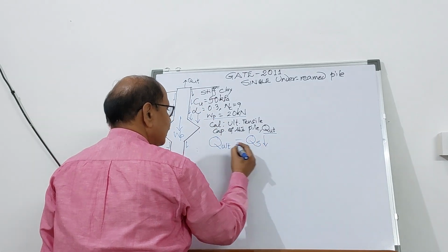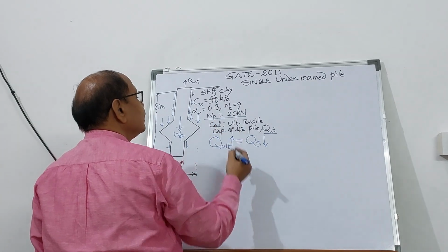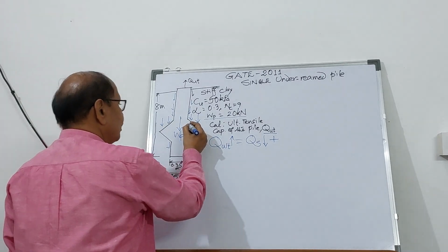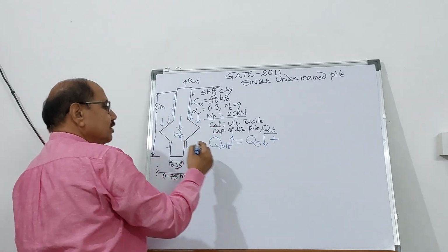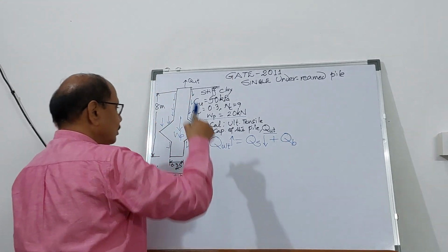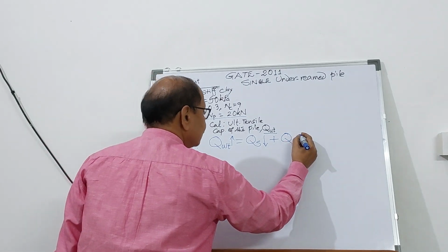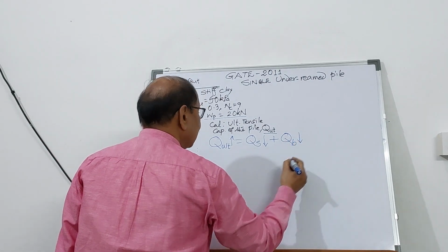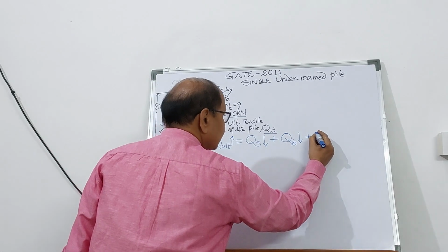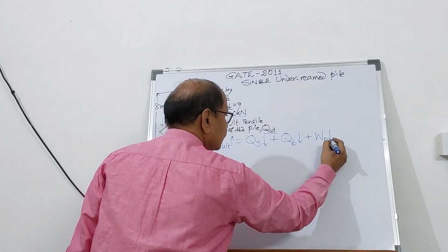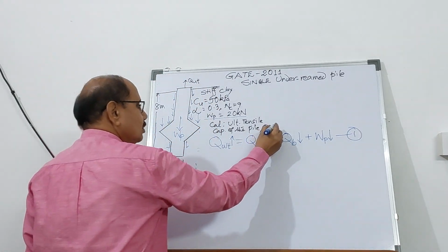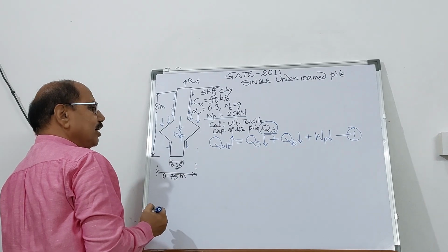This is acting in the downward direction, and this is the tensile capacity, plus, now, over the bulb the resistance is being offered. So, what is the resistance offered by the bulb? That is also acting in the downward direction, plus the weight of the pile is also acting in the downward direction. So this is the expression that you need to use to find out the value of the ultimate tensile capacity of the pile.